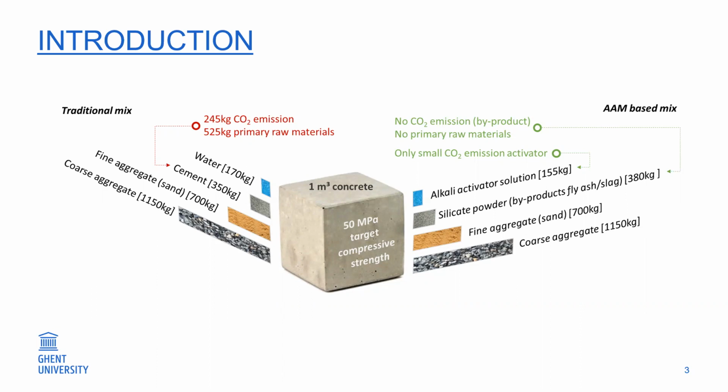Alkali activated materials are produced by activating an aluminum silicate precursor, which can be ground granulated blast furnace slag, abbreviated as GGBFS in this study, fly ash, stainless steel slag, copper slag, etc., with an alkali activator. Through these years, GGBFS and fly ash have been the most widely used aluminum silicate industrial byproducts for the production of alkali activated materials.